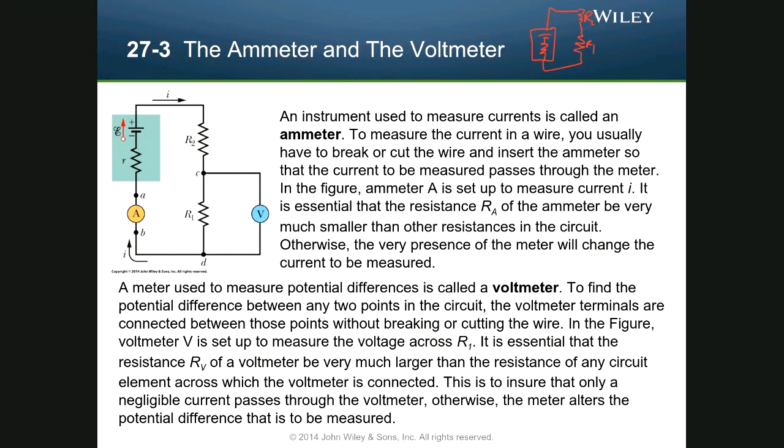This makes measuring voltage really straightforward. To measure current, you actually have to take apart your circuit, right? You have to take apart something here, and you have to put in and rewire an ammeter into your circuit. If you look at it, you can't probe a current here, because if you did, the current would have to leave the resistor and come out, right?